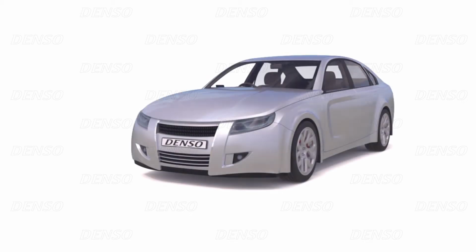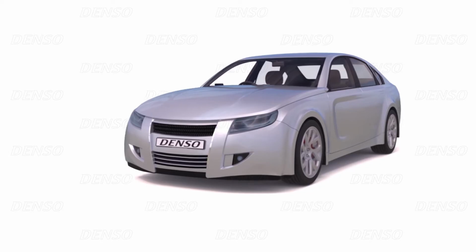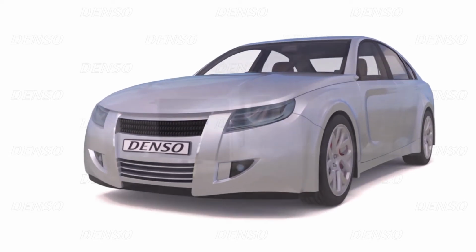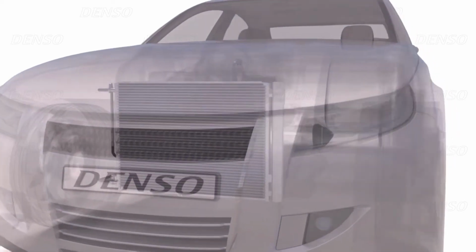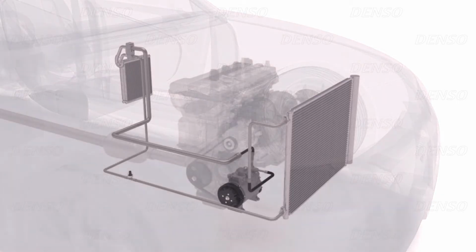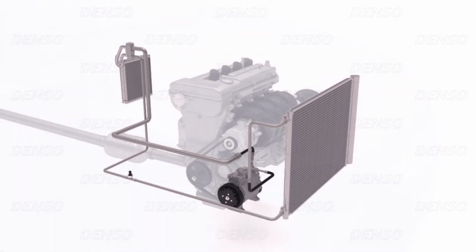Air conditioning systems create a comfortable temperature and humidity inside the passenger compartment, so the driver and passengers feel more relaxed and cool, and the driver is then able to concentrate on driving, which leads to increased road safety. Air conditioning operation relies on taking heat out of the passenger compartment by absorbing the heat into a refrigerant that transports the heat away from the passenger compartment so that it can be released to the outside air.